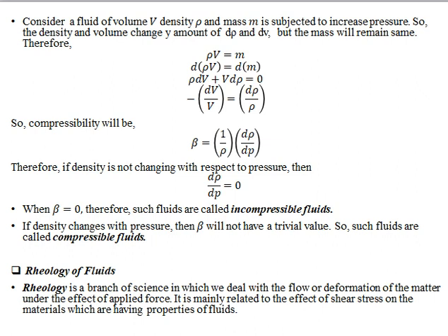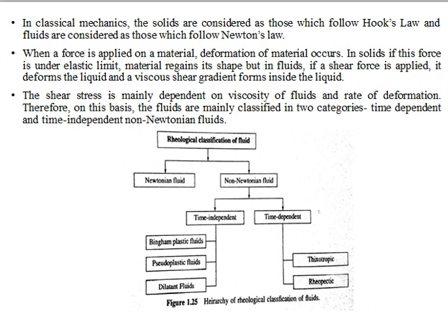If we come to another section of the syllabus, it talks about the rheology of fluids. Rheology is a branch of science that deals with the flow or deformation of matter under the effect of applied force. It is mainly related to the effect of shear stress on materials which have the properties of fluids. In classical mechanics, solids are considered as those which follow Hooke's law, and fluids are considered as those which follow Newton's law.